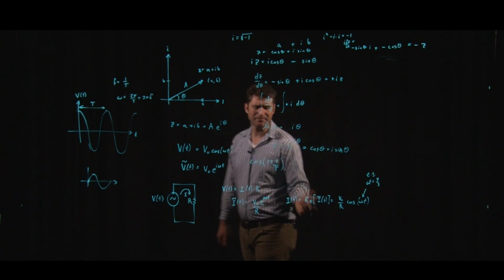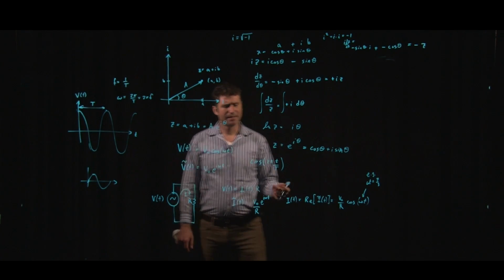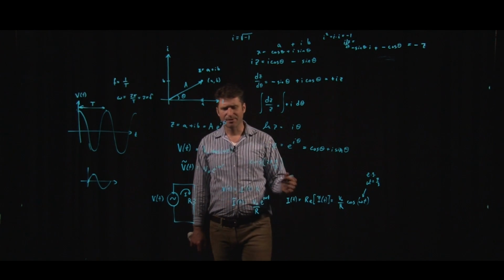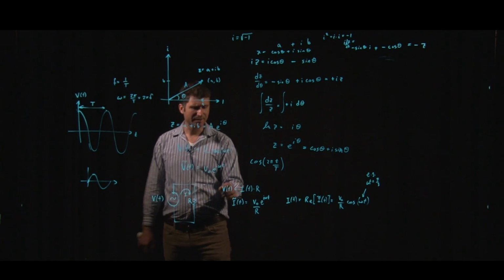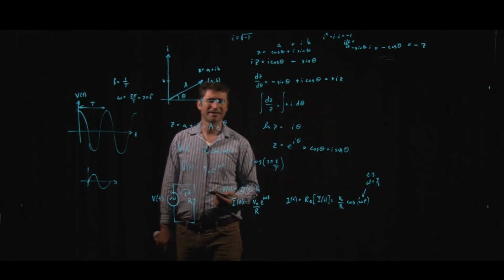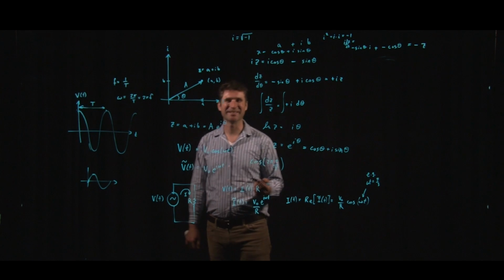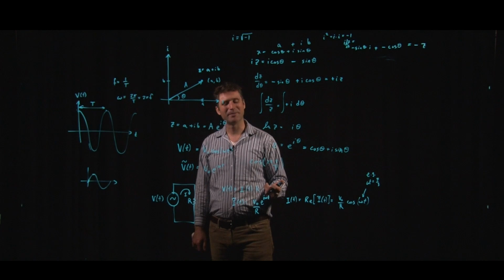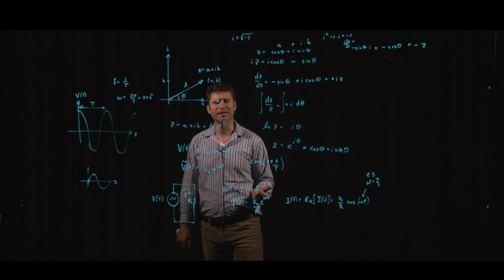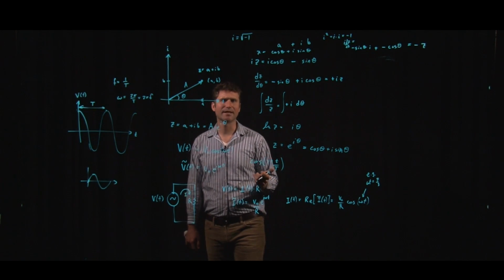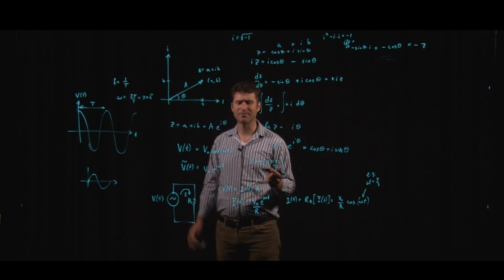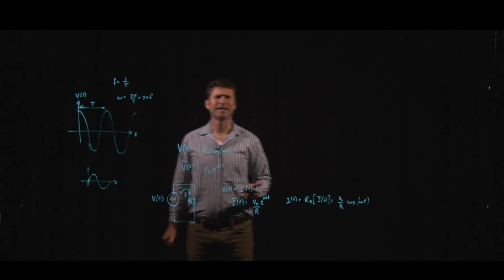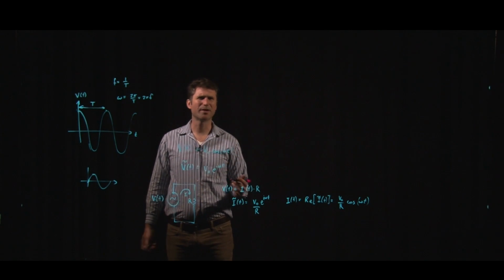And so you can actually then compute the current at any given moment in time that's going through this resistor by using this complex notation. Now, this might seem like a heavy gearworks for just calculating the current through a resistor, but in our next examples with capacitors and inductors, I think you'll see how this is a very useful mathematical approach. Now let's take a look at the voltage drop across the capacitor.